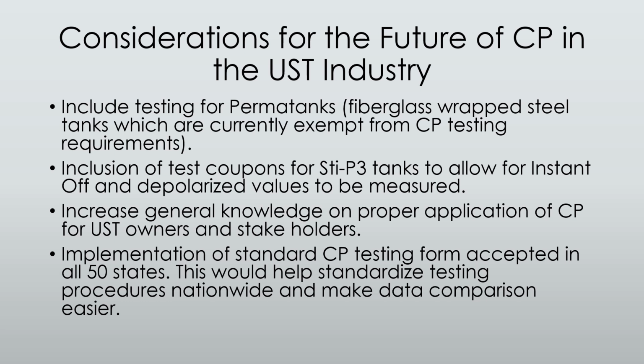Inclusion of test coupons for STI P3 tanks, Type 3 tanks. STI, if you're watching, you should maybe check out some test coupons. Coupons are very widely used in the pipeline industry for systems that have welded anodes that can't be interrupted. So you can interrupt the test coupon as opposed to disconnecting the anode system that can't be disconnected. You can get some more accurate information for those.